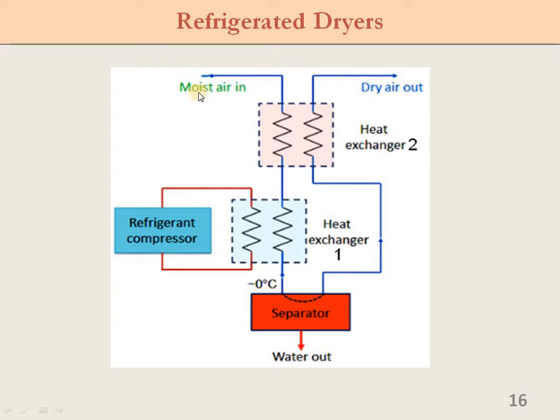Basically, you have already compressed the air using the compressor and it is stored in the container. Before using that compressed air for some application, you condition it by passing it through various components to get the required conditioned air. Once you compress atmospheric air, as you know the atmosphere contains about 85% moisture, automatically that moisture will be there in the compressed air. So you have to remove that moisture content from the compressed air. That's why you pass this compressed air through the dryers.